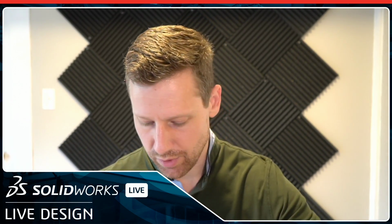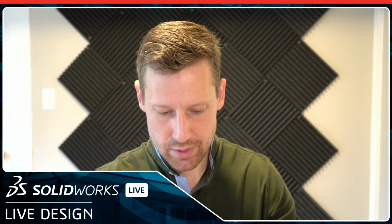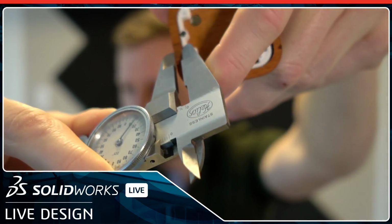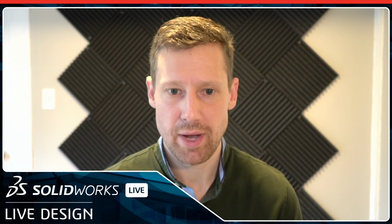And let's say we want a 37 millimeter circuit board, and we need a wall thickness. Let's say we want a wall thickness of, what is that? 4. So we got a wall thickness of 4 millimeters. Let's see if I can zoom that in. There we go. So we got a wall thickness of 4 millimeters, and we can just take this information and go back to our master model.